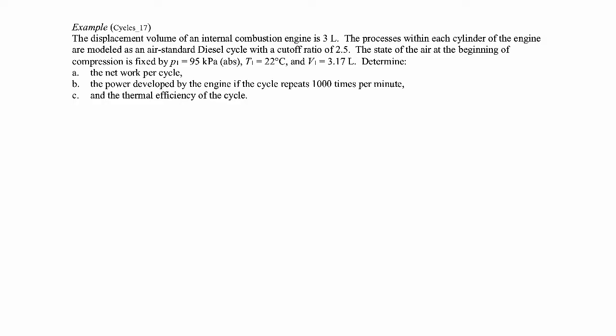In this example, we're asked to analyze a diesel cycle. We have a displacement volume for an internal combustion engine. It's 3 liters. The processes within each cylinder of the engine are modeled as an air standard diesel cycle with a cutoff ratio of 2.5.